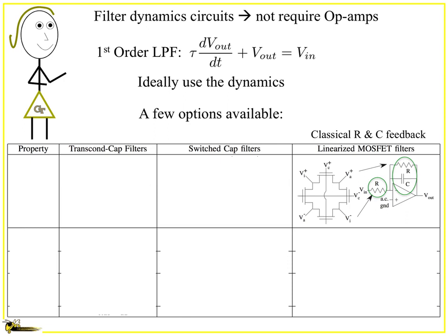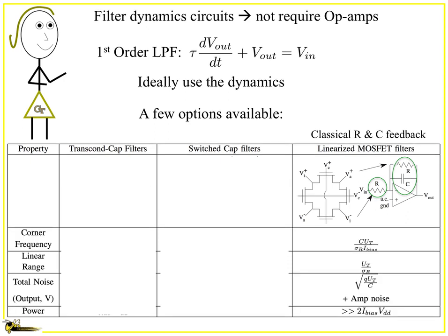But there's your resistors, and you can build some really nice structures out of it. And the things are related to those particular devices. One of the preferred approaches for high linearity, which is what you'd want for good SNR, is to actually use the early effect on these structures. But here's the thing, that op-amp still needs to be included in all of these issues, because that op-amp is usually just kind of like, oh, it doesn't matter, but it turns out to be everything that sets all of these criteria.